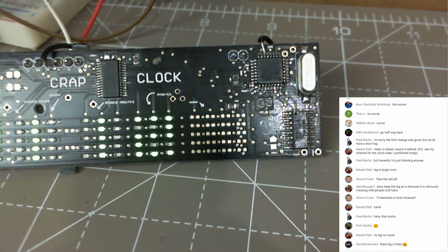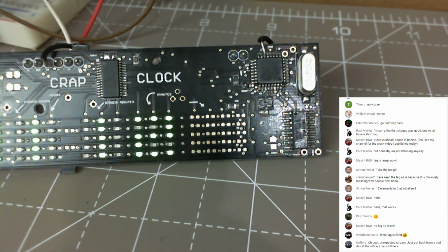So a multiplexed array might have one LED on that row being turned on, and then it would go to the next row, and the next column, and the next one, and the next one. So it's not the same as your normal multiplex display. In fact, the first project I ever did was a multiplexed project, which was a word clock, and that multiplexed LEDs in a grid fashion. So one LED would be lit at a time. But in this one, 16 LEDs can be lit at a time. So it's not the same. But it also makes it a lot faster, which is great.